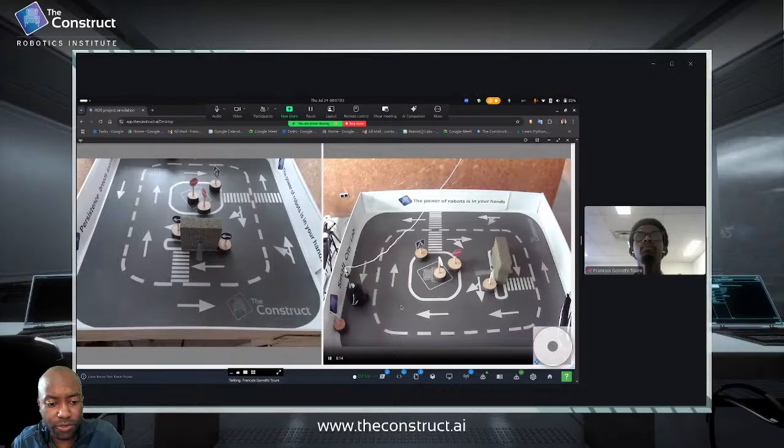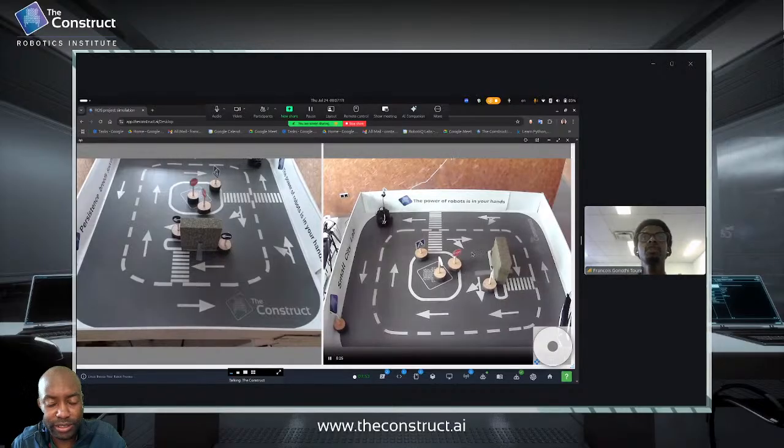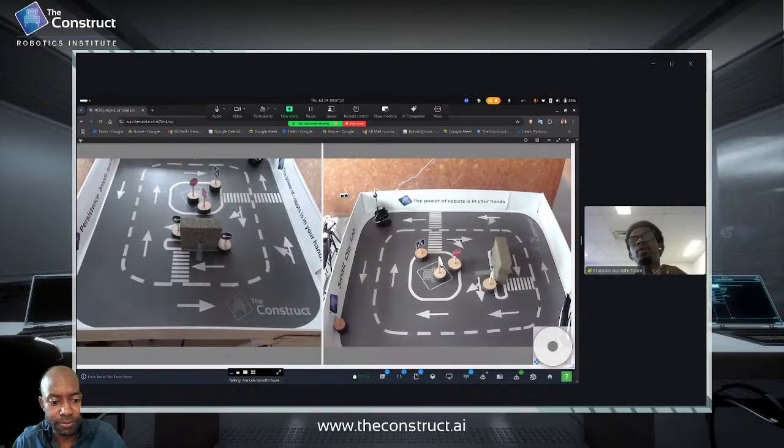What threshold value did you use, and how close can you get to obstacles? I think it was 0.300 for the threshold value. 0.3. Okay. And then it can get close, but we don't actually want the robot to bump into the obstacle. So it shouldn't be close enough to the obstacle, because you should have some sort of security measure. Yeah, it should have some clearance. Absolutely.